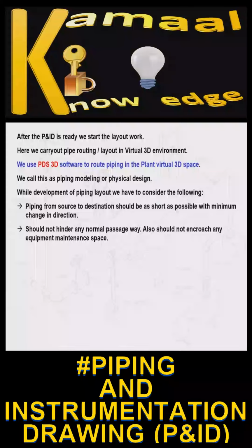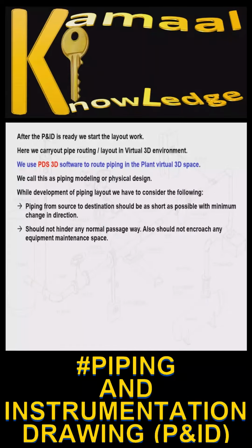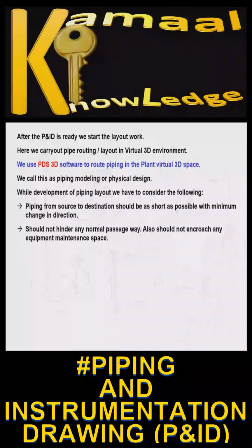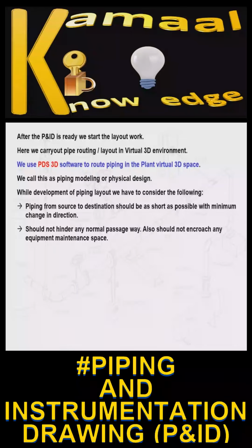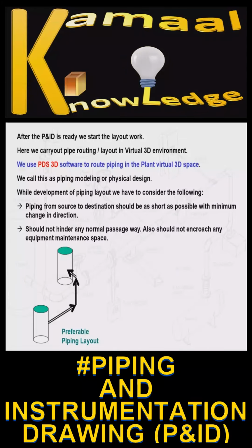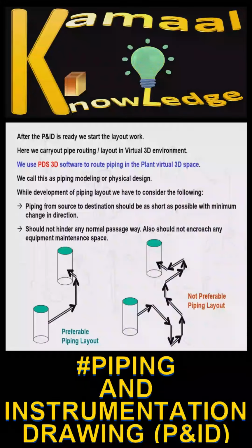While developing the piping layout we have to consider the following. Piping from source to destination should be as short as possible with minimum change in direction. It should not hinder any normal passageway. Also it should not encroach on any equipment maintenance space. Preferable piping layout, not preferable piping layout.